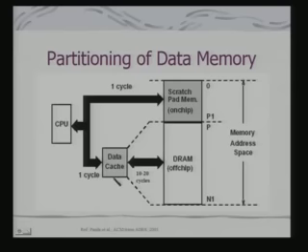This is what we have shown as a data cache. Now, it may have instructions as well as data, so I have got a unified cache. There may be separate data and instruction caches, and that will be the case with Harvard architecture. Here we are simply showing a data cache, and what is interesting is that this data cache is mapped onto the address space of the DRAM, and that is typically the feature of cache memory.